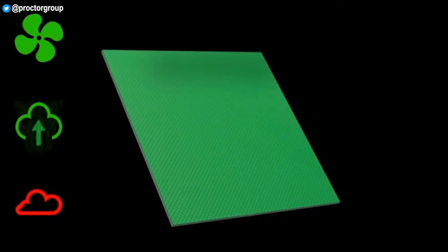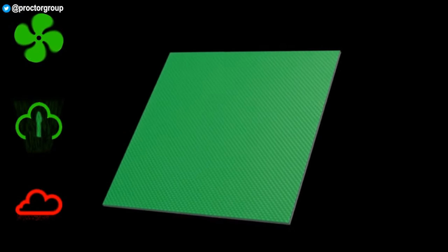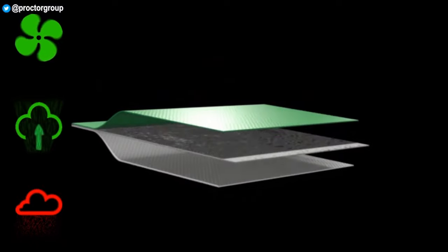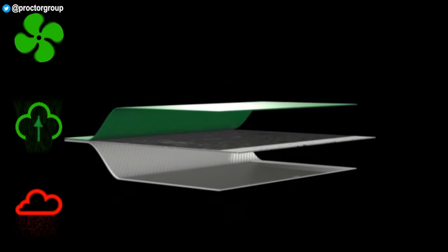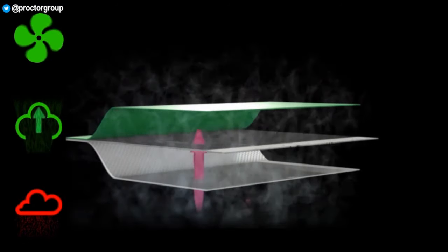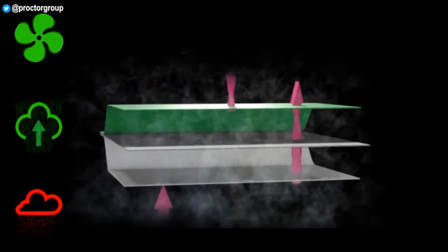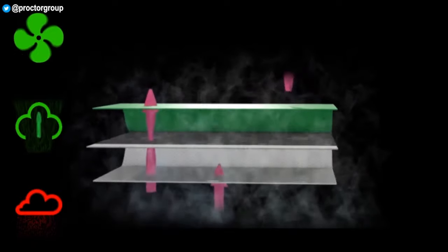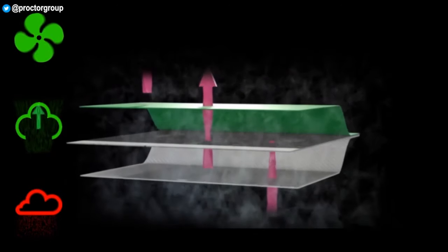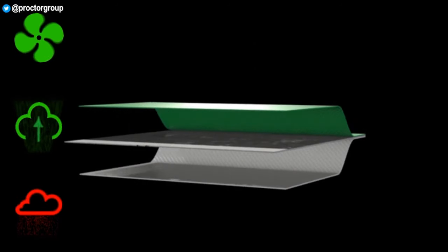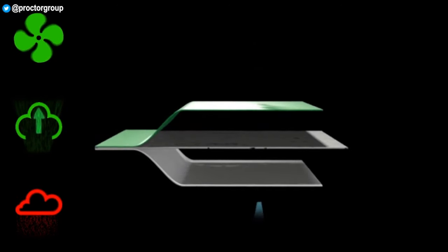Air open vapour permeable membrane. SMS breather membranes comprise a core layer of melt-blown polypropylene sandwiched between two layers of spun-bond polypropylene. These outer layers help provide additional water resistance as well as protecting the core from physical damage. The fibres in the melt-blown core are many times smaller than human hair, giving the membrane a microporous structure which allows water to pass through as a vapour but not as a liquid.